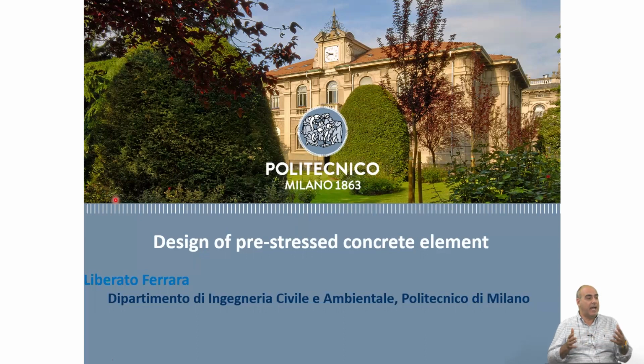So that for natural temperature excursion, which is something that even a completely unloaded structural element would experience, they have a similar deformation. So this implies that temperature deformation equally acts on two materials and does not induce what we call eigenstresses. So are inner stresses which are self-equilibrated, but locally they can disrupt the continuity of the material.